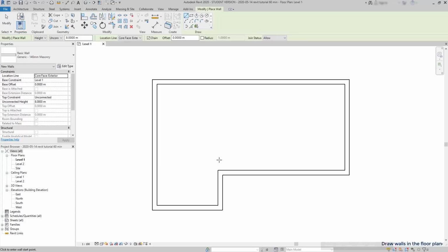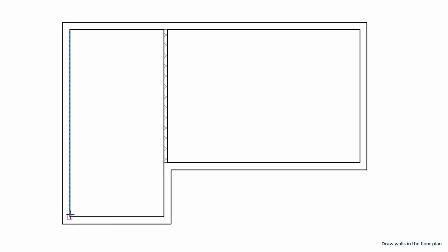And it's not very important which wall I start, because in Revit, it's quite easy and intuitive to change the position of the walls after drawing. You will see. I start with this vertical one, because I know it intersects this corner. Then, the wall that divides the left part in 2 rooms is located at this distance of 3.8 from that external wall. One good way to make it is going to the endpoint at the corner, drag up and type the distance.